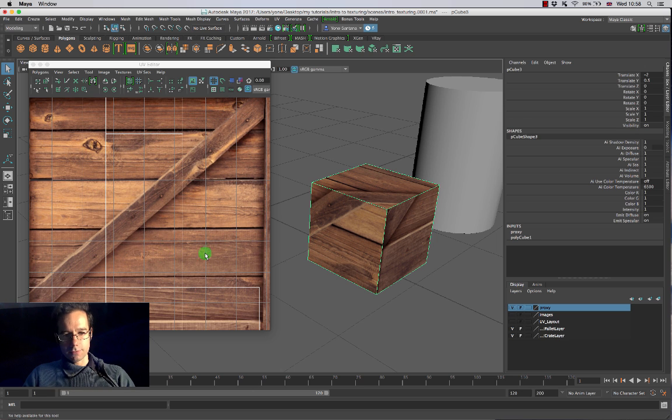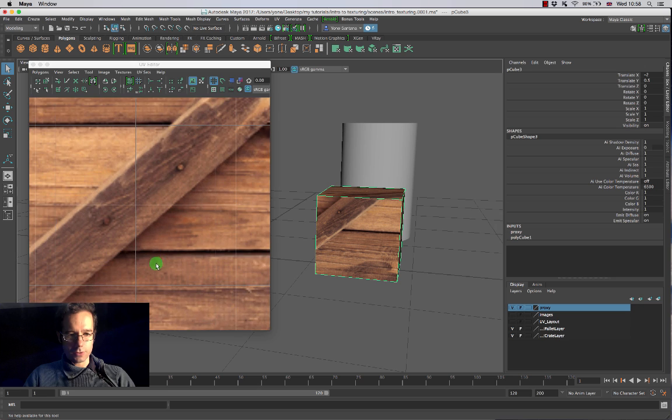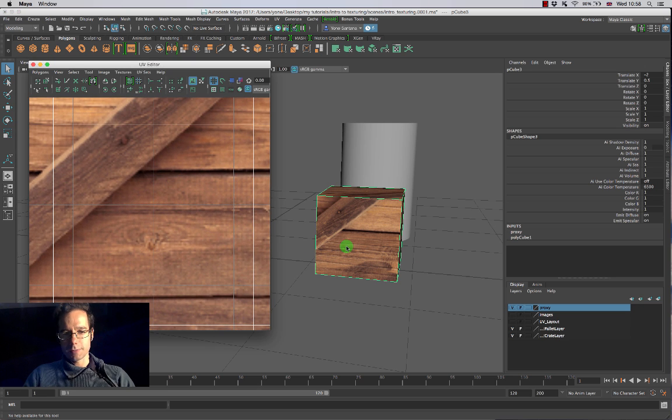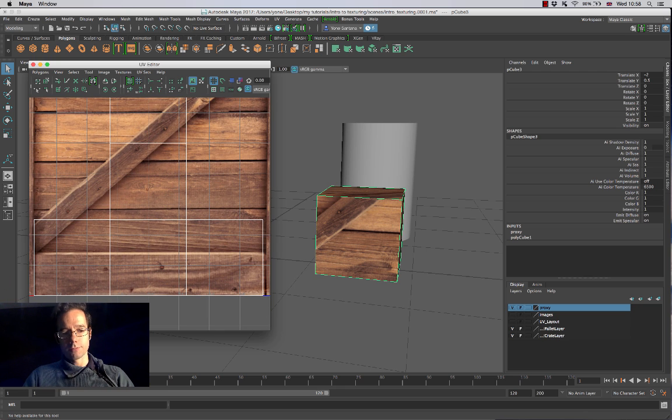And if I look at some individual faces over here, I can see that this little triangle over here in the top corner and this little section of the crate is actually being projected into this face over here. So if I zoom into it, you'll see that these look very similar. This is because UVs apply 2D coordinates to 3D positions, and that's why they're called UVs. We have X, Y, and Z for our movement inside of the 3D workspace, and the letters that come before that are U, V, and W, which we don't use because it's 2D space. So importantly, our UVs and our 3D viewport are connected together in a very specific way.